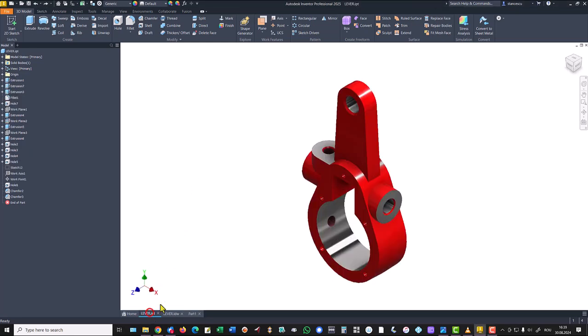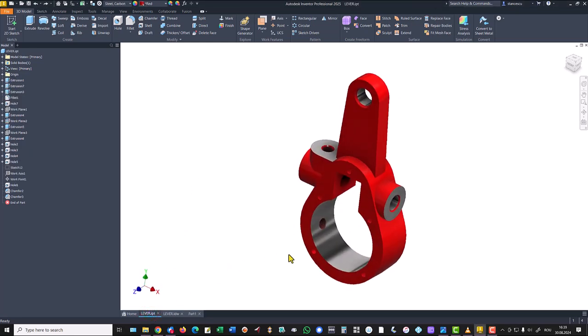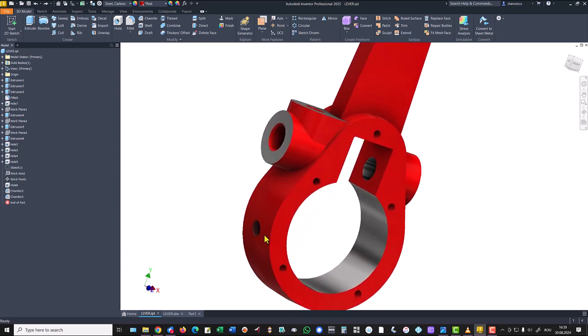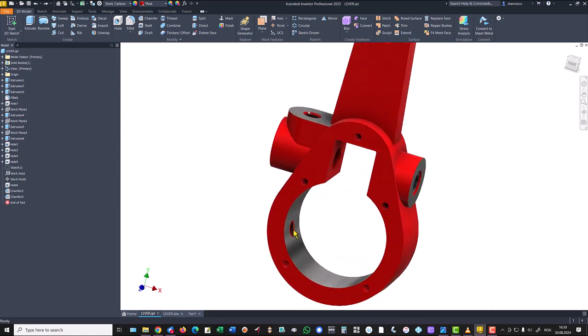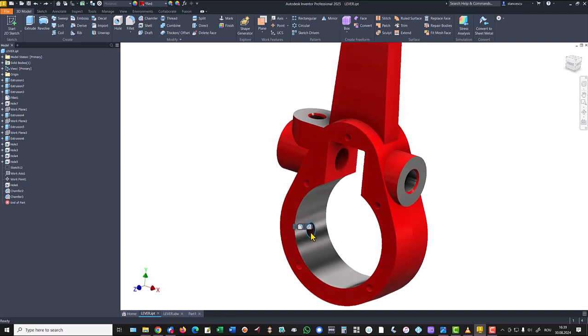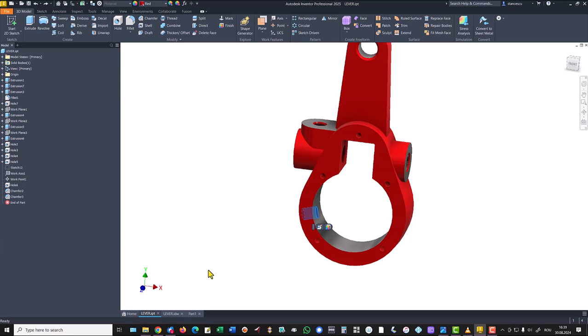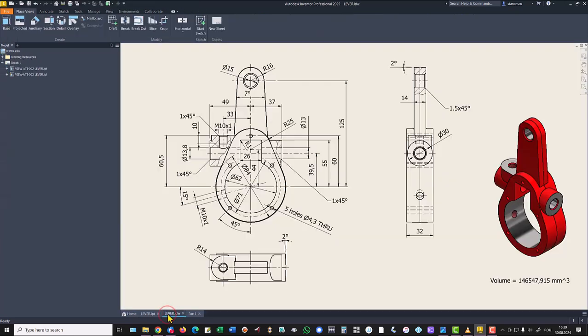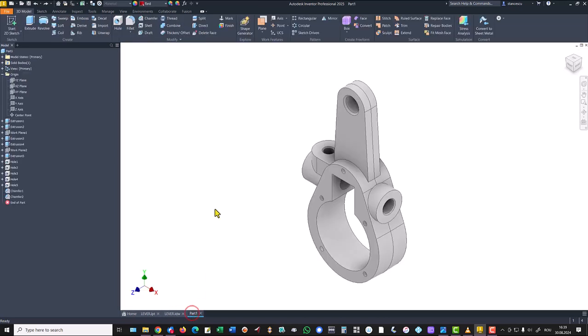The last feature is this hole. You see, it is a sloped hole. We have dimensions, metric 10 with a pitch of 1, just like this one, at an angle of 15. Now we apply a special procedure.